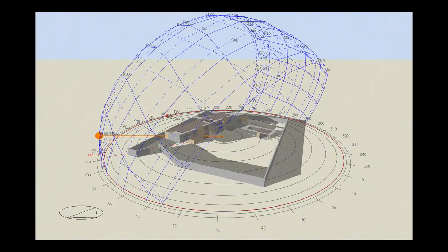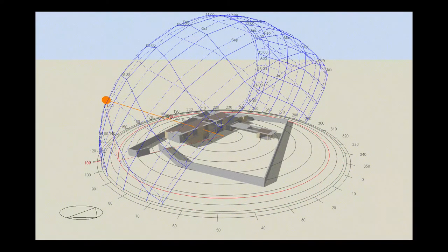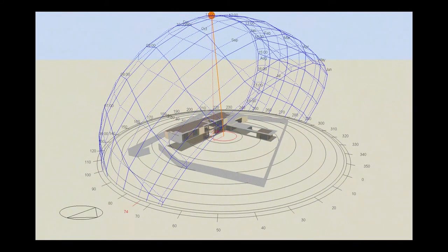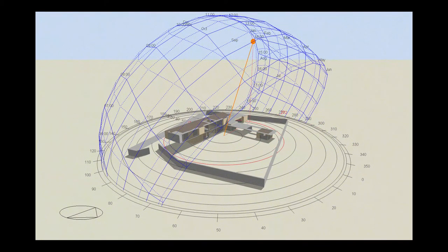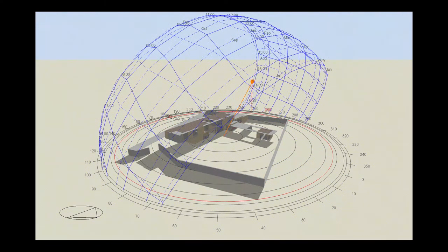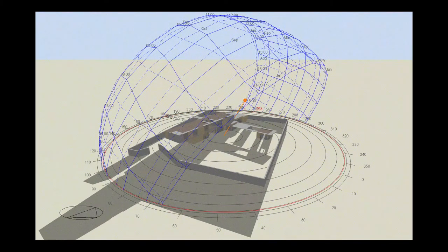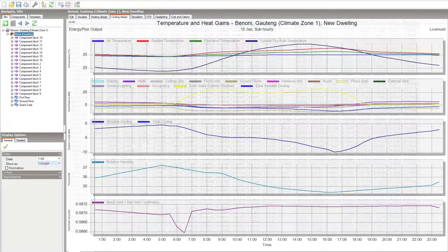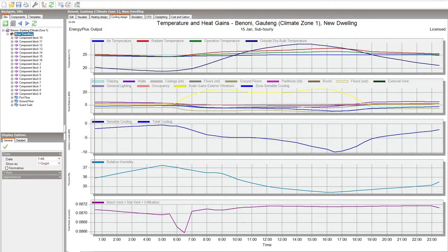Our simulation modelling is immensely intense. We develop a 3D model of whatever your project is. Then we run sunpath checking algorithms over that model using real-time localized meteorological weather data that is programmed to stop every 10 minutes, 365 days a year through those simulation runs to analyze and report on all the direct and indirect heat gains and losses on every single element of that building. The data that we get to analyze is immense.